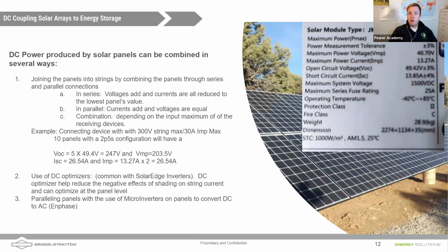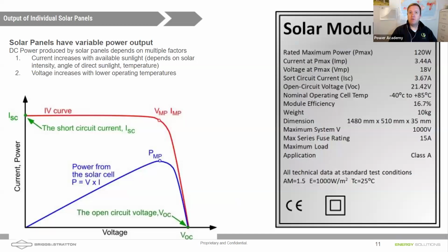Temperature and also the power point of where we're going to be drawing down. One thing I wanted to mention, Nathan, is on the previous screen, we had shown the maximum power point of the voltage at 18 volts. So this must be like a 36 cell module, which for me back in the day using old PWM charge controllers was pretty close to where we needed to be able to charge a 12-volt battery bank.